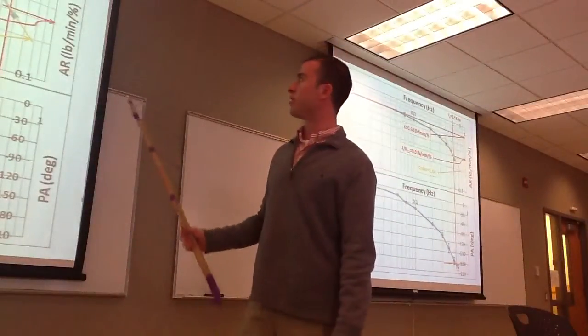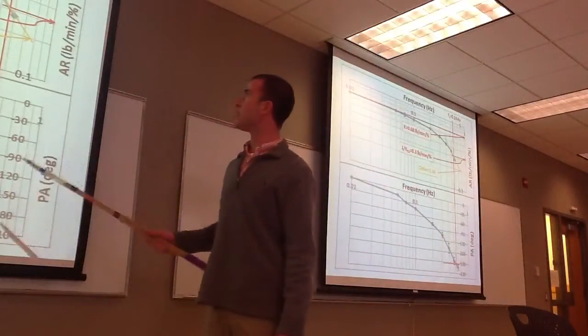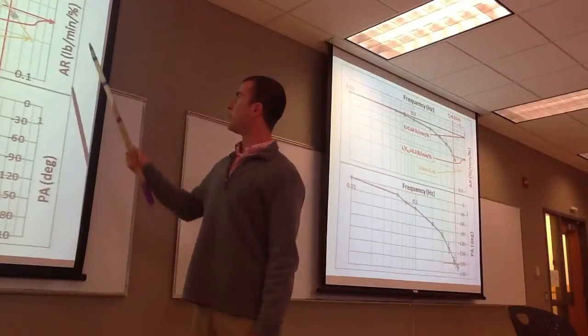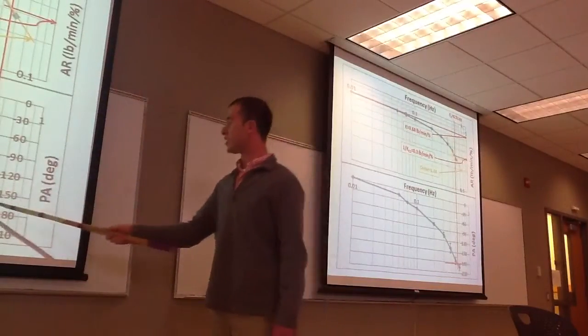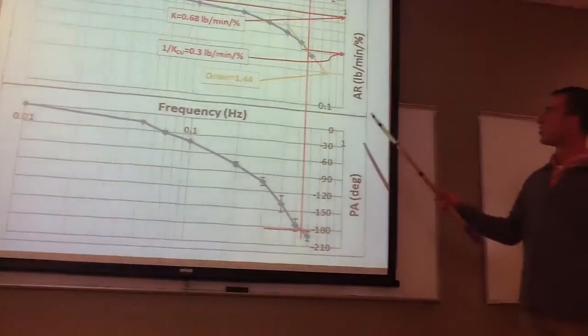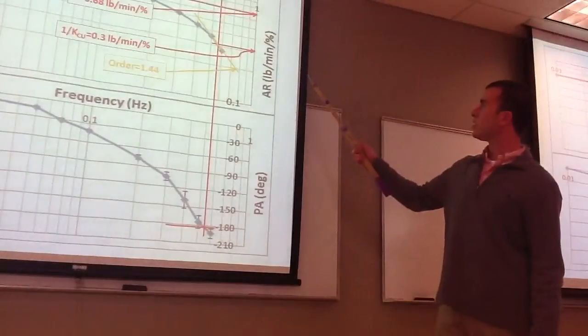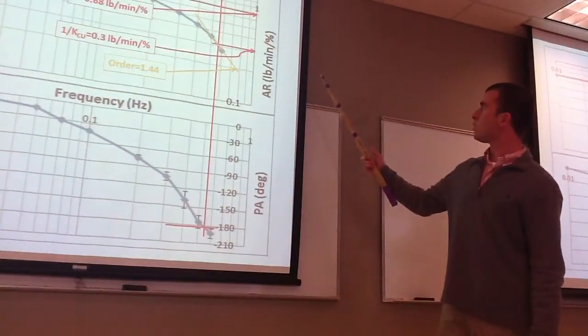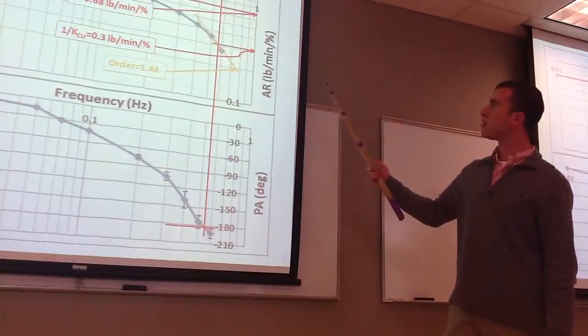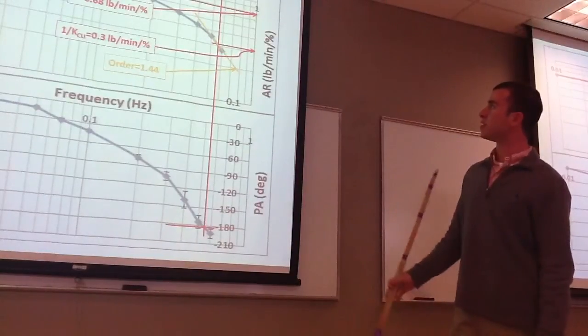Here's one of our Bode plots from our system. Shown here is an ultimate frequency of 0.53 hertz, which occurs at a phase angle of 180 degrees, and an amplitude ratio of, I believe, around 0.4 pounds per minute per percent.